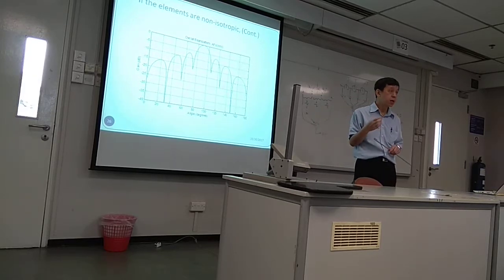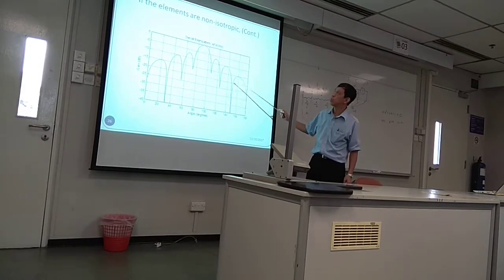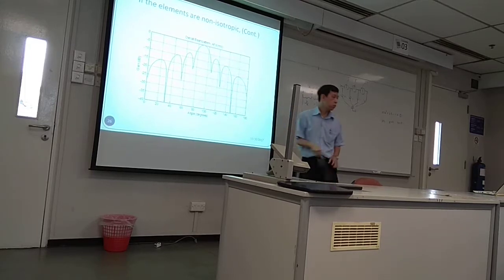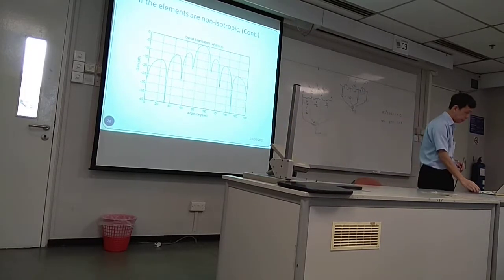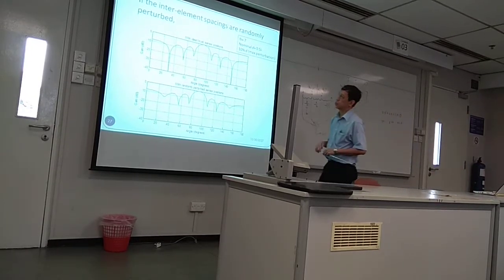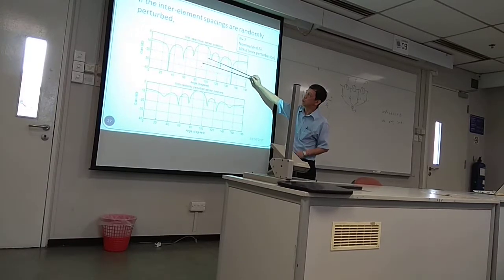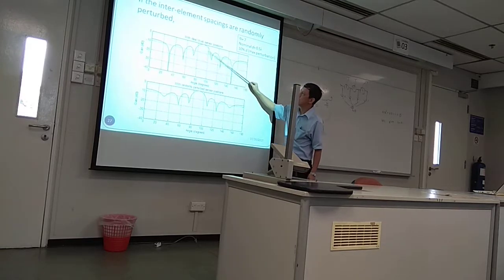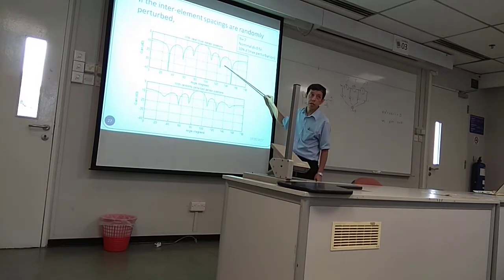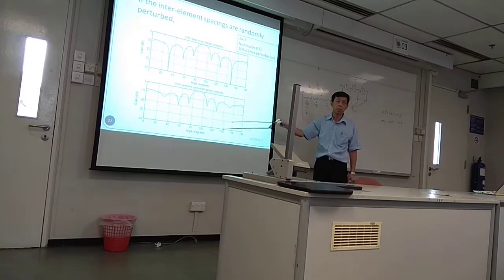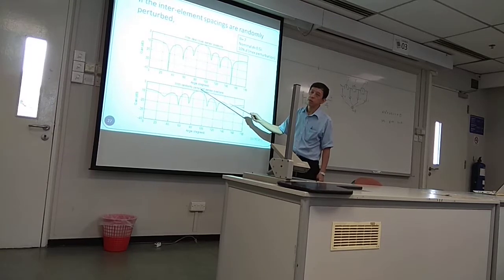Alright, so that is how we obtain the overall beam pattern, and that is the array factor multiplied with the individual array element beam pattern. That is so-called pattern multiplication. Okay, now this is basically just to illustrate to you, theoretical derivation versus real life pattern. An ideal linear array may give you a beam pattern that looks like this, but when you implement it and measure it, it may end up to be something different, not exactly the same, and that is so-called perturbation.